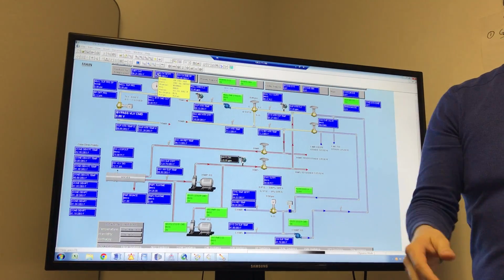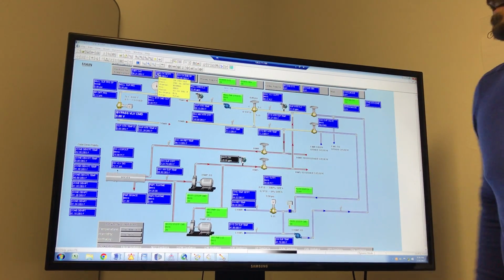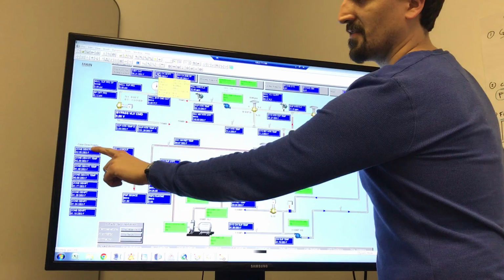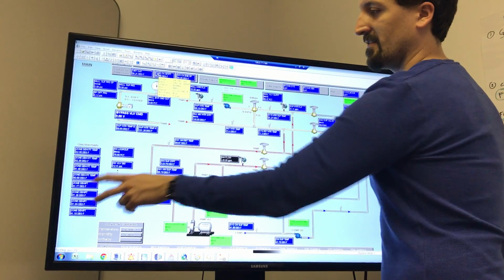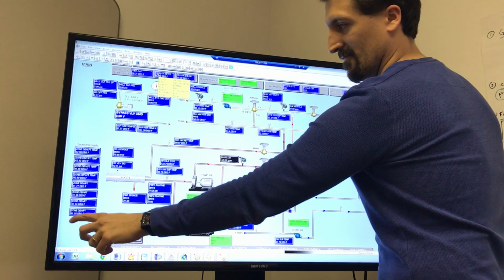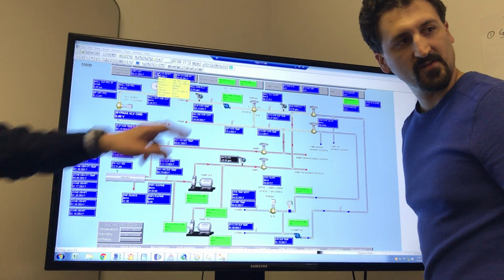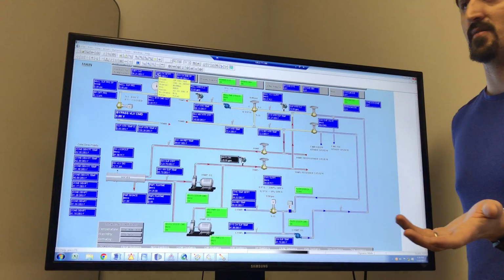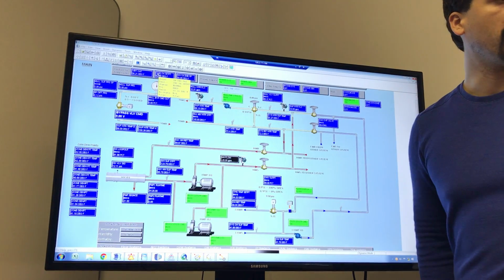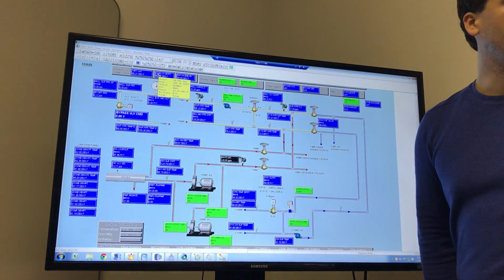It's the max or the lowest you can do. And the lowest you can do is the maximum value of your zone dew point. So here will always equal max of this. You don't want to go below the dew point. So if the dew point is 55 and our set point is 55, that's where you start to get stuck.